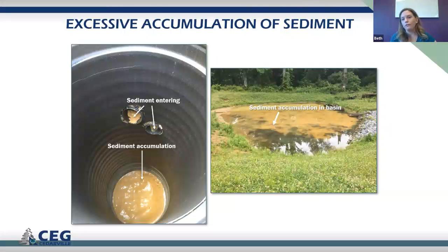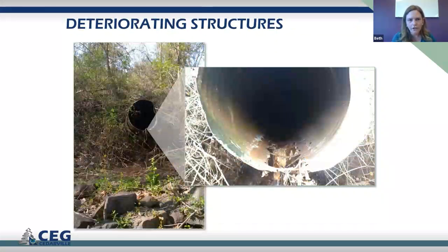And same over here for this basin. There's sediment accumulation in the basin. It's important to remove it. And if you pump it out, it has to be pumped through a pumped water filter bag. It can't just be pumped directly into the stream. Or if it's over a really long vegetated surface, I think a flat surface, you just have to be careful about sediment discharges. The township may not be responsible for cleaning the sediment, but you need to make sure that the responsible party does do that.